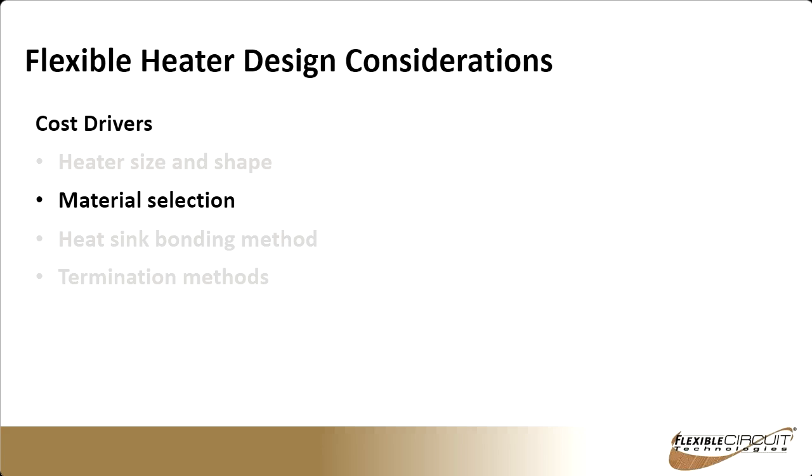And the heater bonding method, we talked about that a little bit. PSA is the least amount of processing to apply, and so that's going to be the least expensive solution. If you're using a thermosetting adhesive, because that's typically done in a hydraulic press, that can be more complicated. It's typically something we have to do in our facility. And if you have a 3-dimensional object that you're attaching it to, that usually requires some fixturing also in order to properly adhere the heater.